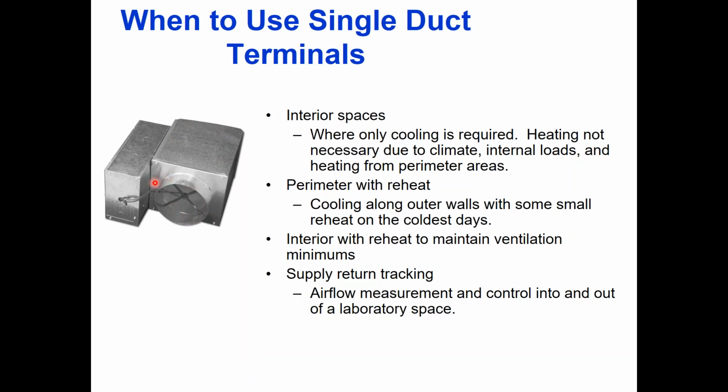There are some characteristics that we'll point out here. Normally, and by normally I mean just about every single job, there's a round inlet and a rectangular outlet. That is pretty common. And the round inlet is smaller than the rectangular outlet. So when air comes in here at a certain pressure, because the space gets wider, it's going to be leaving here at a lower pressure. One of the jobs of the VAV air terminal is to be a pressure reducing device.